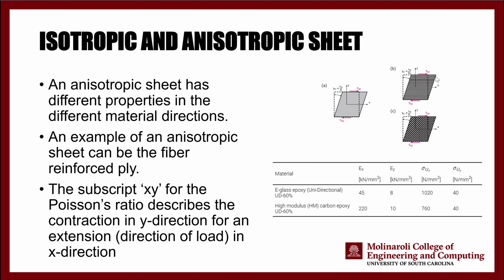Essentially, a unidirectional composite is where you have one direction in which the carbon fibers or glass fibers or whatever are placed, and then they are connected to each other using epoxy. So if you apply stress in this direction, they won't be able to resist this stress, and the material easily breaks. But in this direction, the material is very strong.